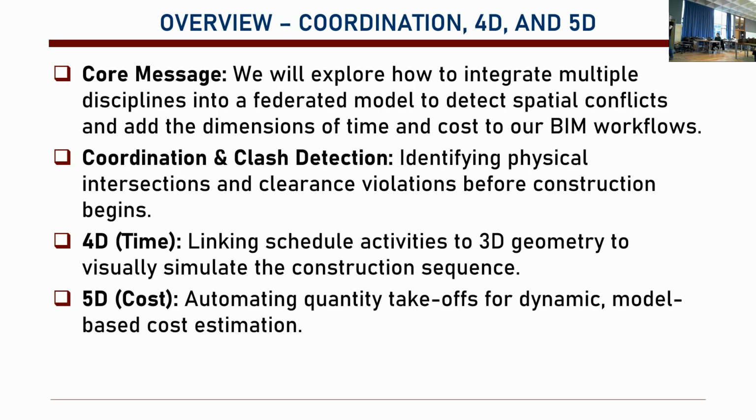Coordination and clash detection is all about identifying physical intersections between different, let's say, discipline inputs, and also clearance violations. So sometimes we have these. And 4D is basically the time, and we basically add the schedule activities. Schedule is like, you know, the time list of different construction tasks, for instance, okay, to 3D geometry, so that we can visualize and simulate the construction sequence.